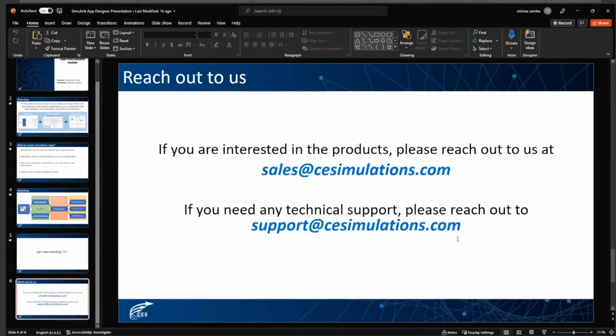But this will be controlled by an external process. So one solution I can suggest is that you make two apps, okay? One app will be controlling another app. So you make a simulation app like what we have done for the Simulink, and another app to control the simulation. But for this model, can we use the Simulink Compiler and the MATLAB Compiler as well, or do we need another component like MATLAB Coder or Simulink Coder? I don't know. You need MATLAB Compiler and Simulink Compiler for this case.